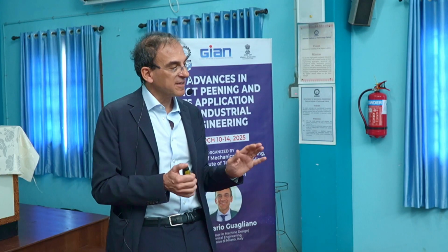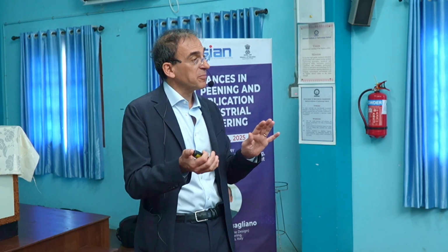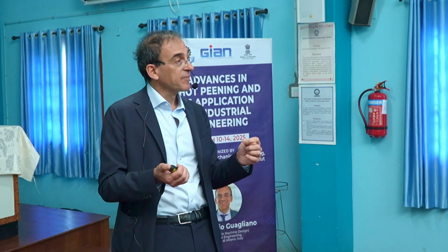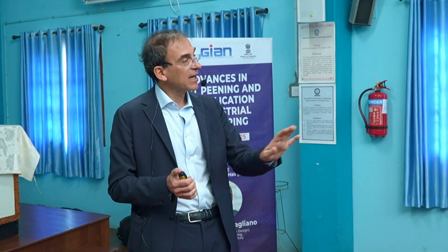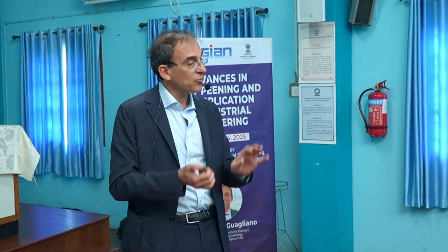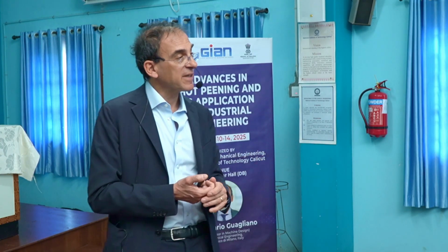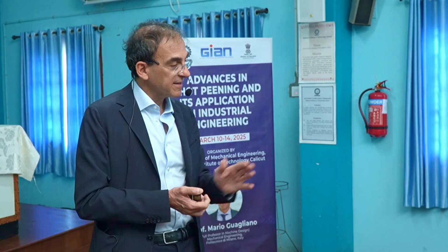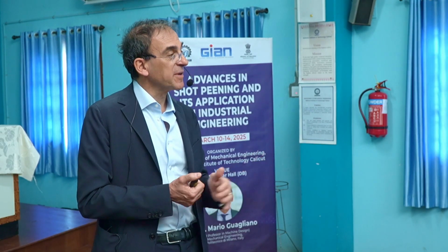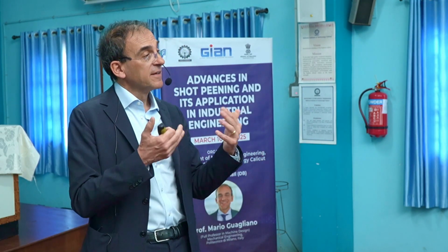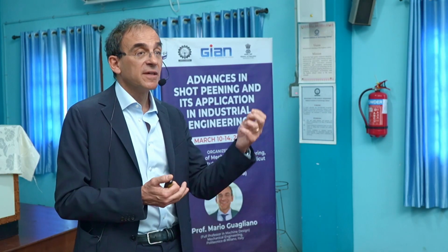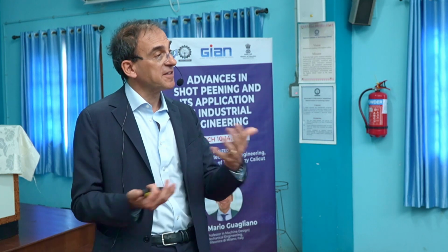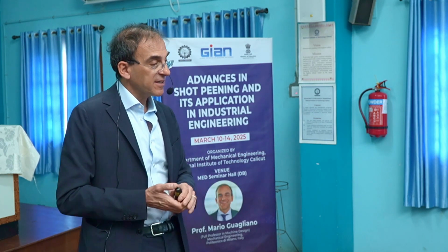Okay, and then finally, when the Almen intensity is measured and it corresponds to the one that we considered during the design stage, we can peen the part according to those parameters, to respect the design Almen intensity. Indeed, we are performing shot peening, of course, after having designed the treatment. And designing the treatment means that we have already chosen the Almen intensity and the coverage, which is the other parameter we will see in a while.